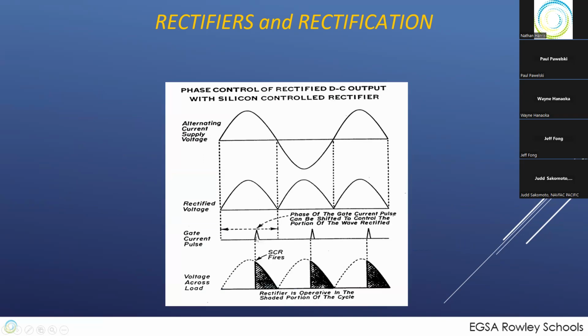If you send a pulse through and use that to turn on an SCR, what you'd see is absolutely no power on the output of the SCR. Well, almost nothing, because there's always leakage. Then all of a sudden, boom, there it is. And you'd see it until the power on the load coming in goes to zero. As soon as it hits zero, boom, the thyristor stops letting power through, and it won't let any more through until something hits the gate again. Boom. Why is this important?